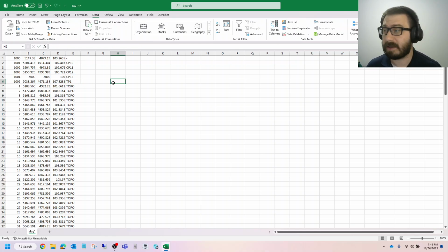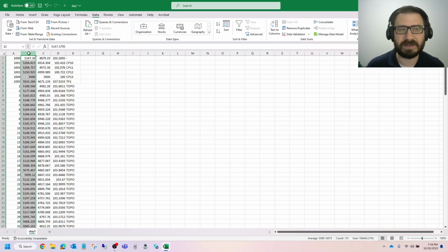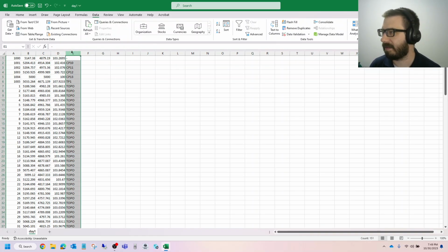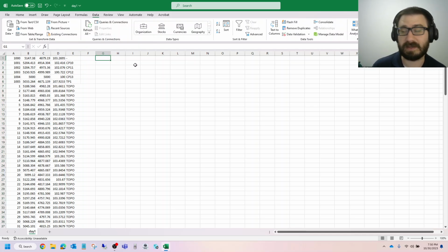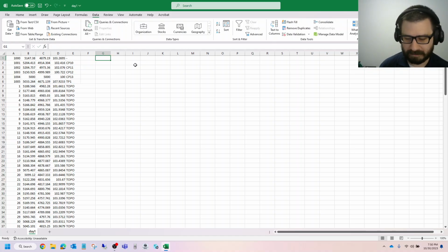So when it's all said and done, you should have a row dedicated to every point with no header. And what you should have is the point number, northing, easting, the elevation, and then the description. So if you wanted to describe the file in letters, it would be PNEZD: the point number, the northing, easting, the elevation, and the description. I typed out that PNEZD because you're going to see that code here in a little bit in AutoCAD. But this is all processed and ready to go.